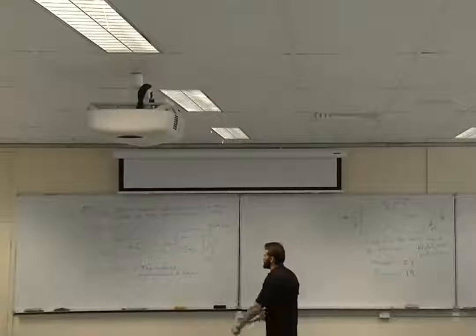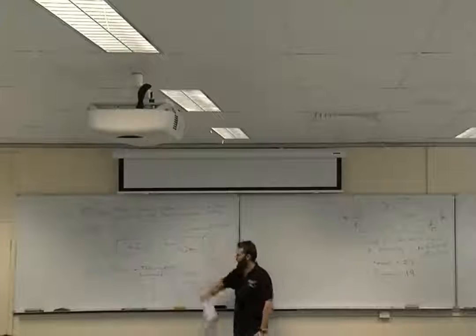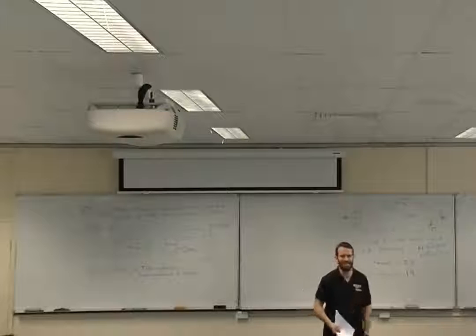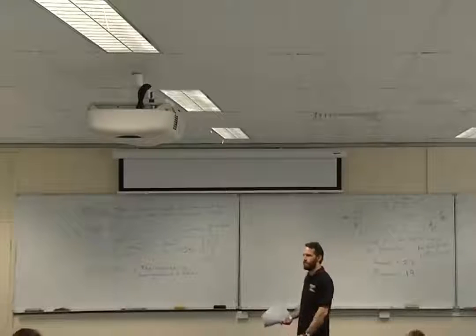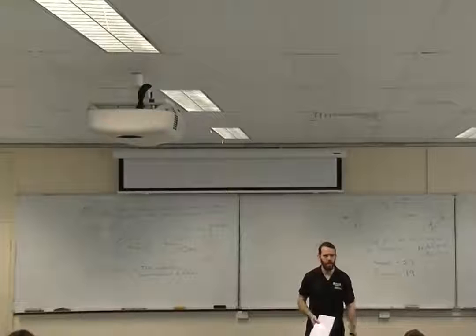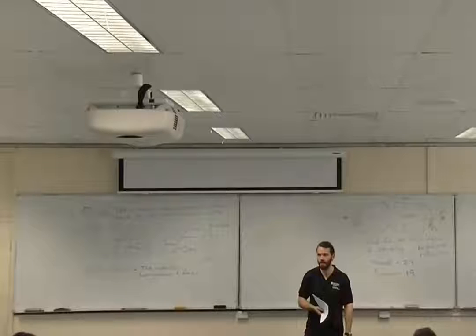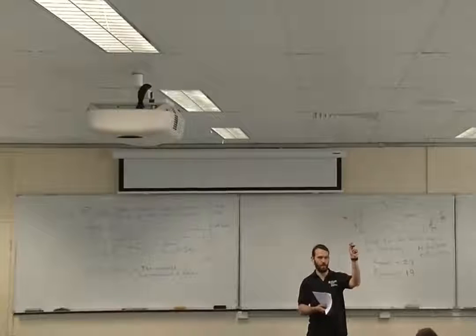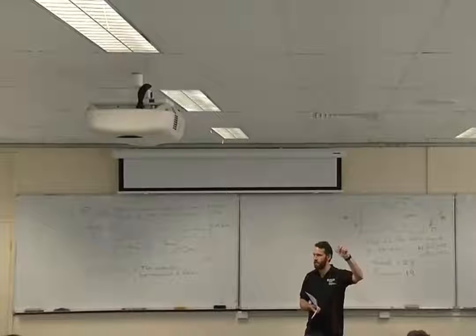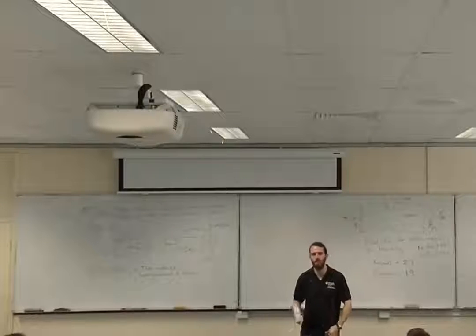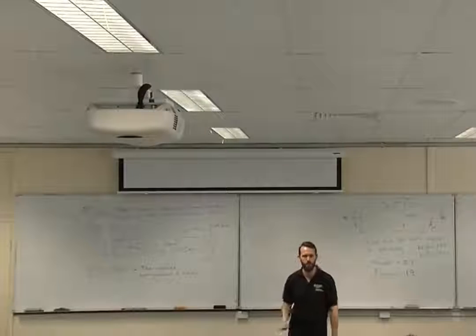And homogeneous just means it's the same material properties everywhere and it's consistent, so it doesn't have little things like bubbles and voids and problematic bits like that. It's been manufactured well. Now, if I had tiny little bubbles in this, what would happen at the tips of the tiny little bubbles? Stress concentration. And so if we have tiny little bubbles throughout the cross-section of something and we've got massive stress concentrations, remembering that a tiny little bubble is about as bad as a little crack, we've got bad stress concentration, and so bad material equals failure very, very quickly.